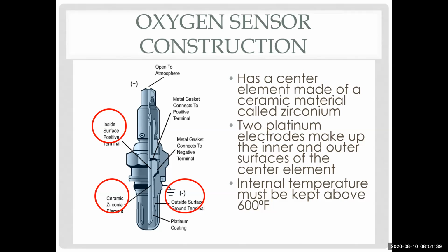But it is critical. I fixed a lot of cars simply by taking the O2 sensors out that a customer put in and putting the correct sensors in. And I've gotten paid diagnostic time to figure out that was the problem, as well as paid to change the part and everything else, because the part they put in was not correct for the vehicle. Even though at XYZ Auto Parts, the sales guy at the counter looked it up in the catalog and said that's the one that fits. Fitting and being correct are two different things, and for oxygen sensors, that's critical.